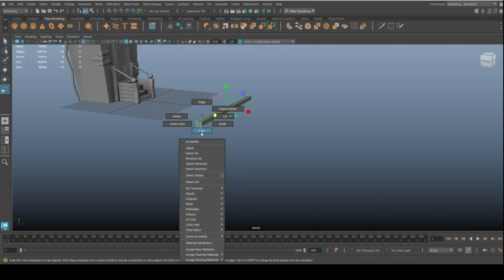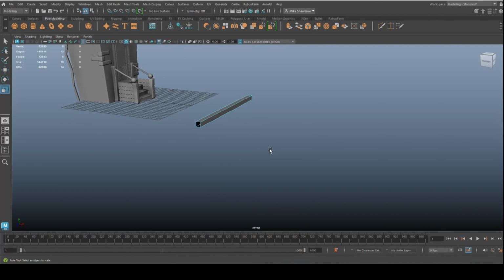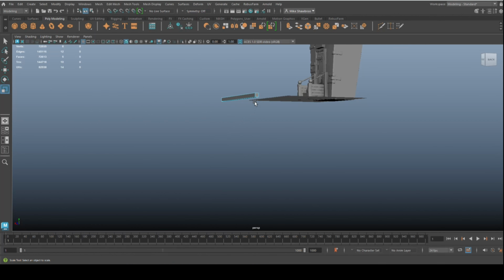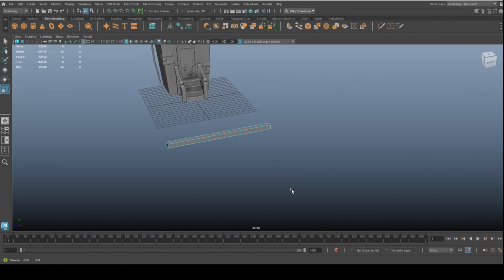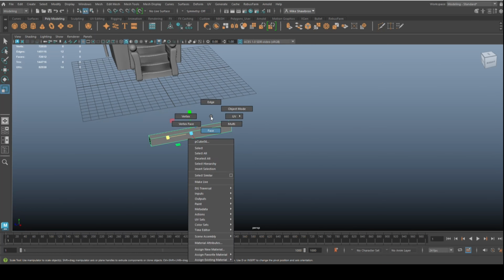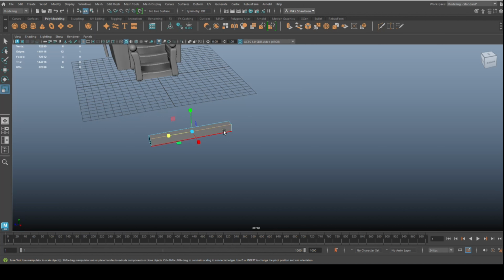We're going to go in here, we're going to go to face, delete that one, and delete that one. And these are going to be segments, right? So we're going to push this in to about here. We're going to go into this guy, and we're going to hit bevel, and then we'll do 0.2, that should be fine, and then 3 segments, that should be fine.